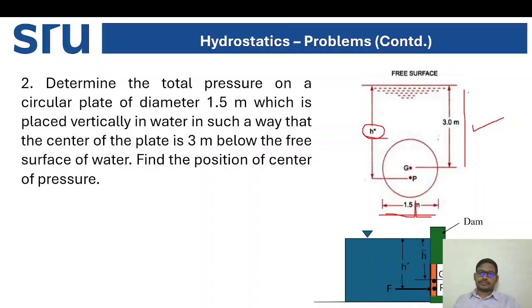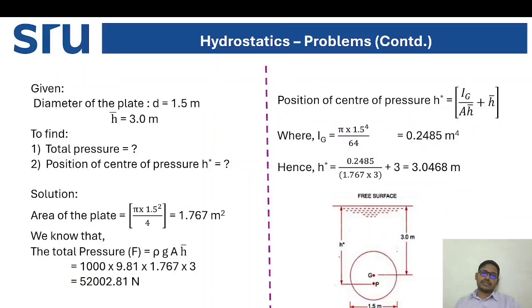Imagine there is a dam and there is water we are storing, and this is a kind of circular gate opening instead of a rectangle. So there will be a center of gravity and a center of pressure. The center of pressure always acts below the middle, with respect to pressure. Now we are going to calculate.